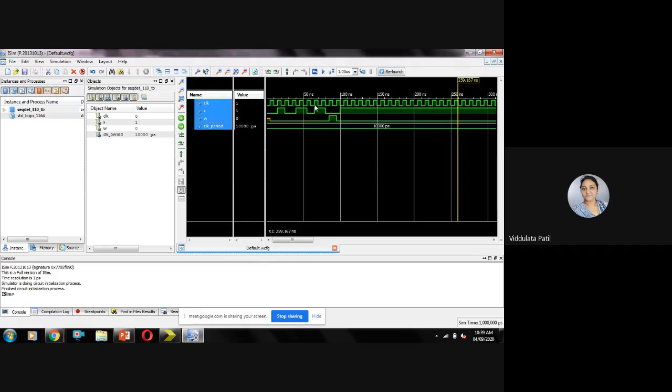But for this clock signal the input is high, then again here it is going high, and after that for this clock signal it is low. So you are getting the sequence of 110. Here you will find that at this rising edge of the clock the output is going high, it will remain high for one clock cycle and again it is going low. So this is the sequence detector for the 110 sequence.